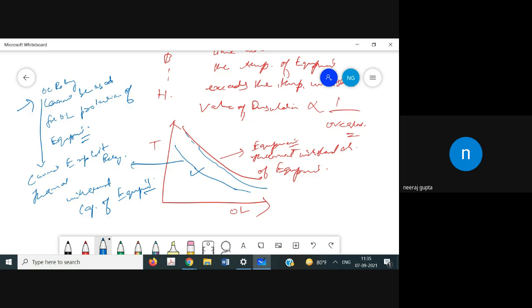If you take the characteristics of the overcurrent relay, it is near this point, because we have to disconnect the equipment in a fraction of milliseconds. Let us suppose this is the characteristic of the overcurrent relay, and the equipment is capable of taking the overload for a certain amount of time. If we use these characteristics, we will still operate the equipment up to this point.